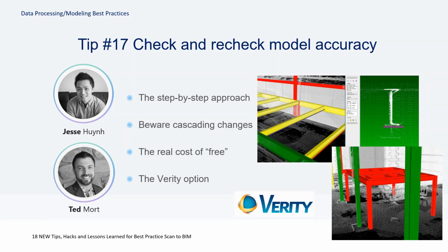So if I have a Scan-to-BIM product, that model, I can put in that source cloud, run this analysis, and see where the deviation occurs to make sure that omissions are acceptable and that everything's within tolerance of the accuracy that we're stipulating. Now, the trouble with that is, like I had mentioned, it's free software, but it takes a lot of effort. So are you ready to suffer the opportunity cost that is building that? And what we're really excited about is some of these new developments that we're seeing in Verity to potentially automate that process of comparative analysis between that product and the source scan.